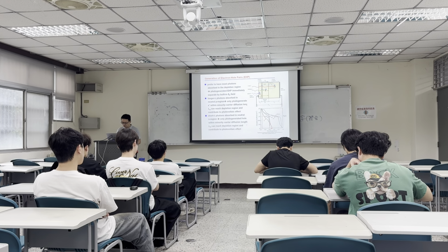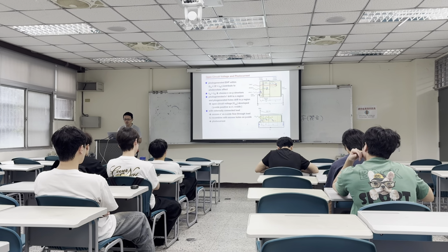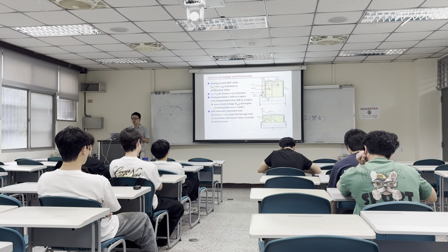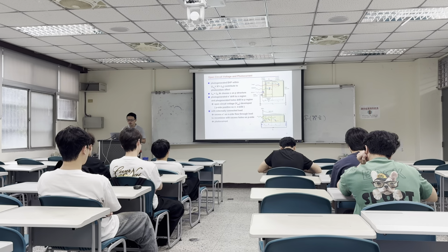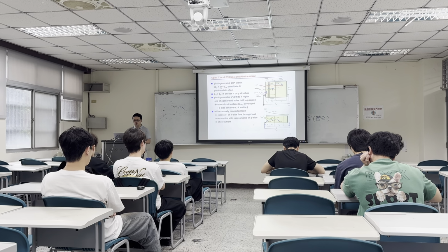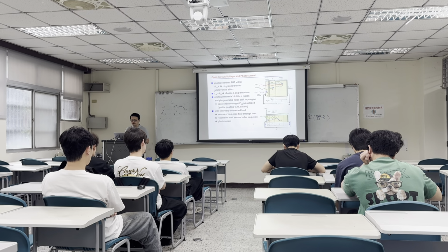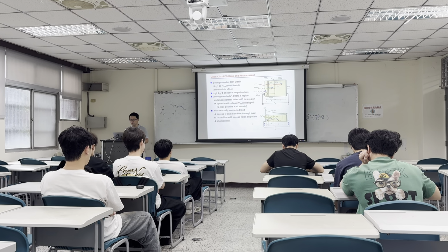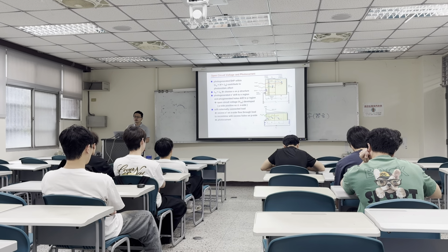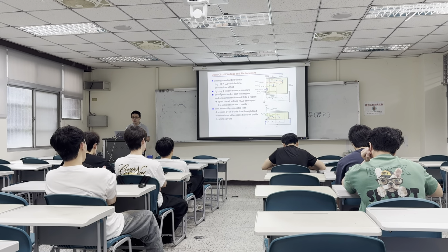Okay, so here, as we mentioned, the photogenerated electron-hole pairs within the hole diffusion length in the N region and the electron diffusion length in the P region can contribute to the photovoltaic effect, only within this range, effective. And usually the electron diffusion length is larger than the hole diffusion length.